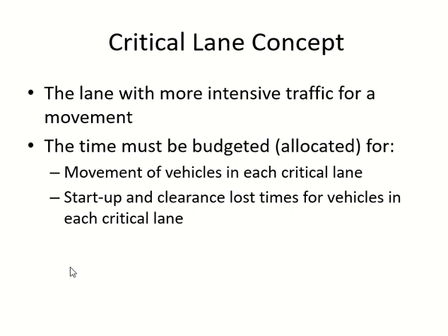Clear? So if you have 3 or 4 lanes and they have different flows, you will take one of them, right? Which one will you pick for your design? The one which has maximum flow, right? Now let's say the flow is the same. You have 2 lanes, one for straight, one for left turning. The flow in both of them is the same. Which one will you pick for your design? Left, because you are on the left hand side, they need to slow down. They take more time.